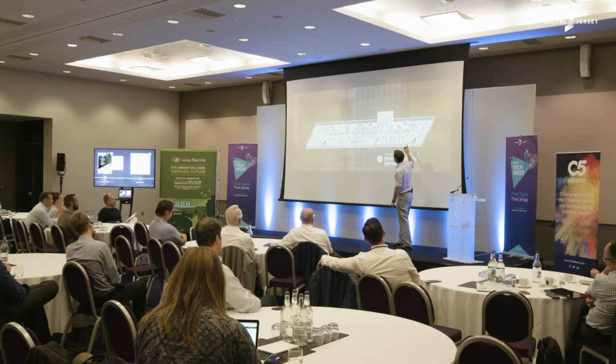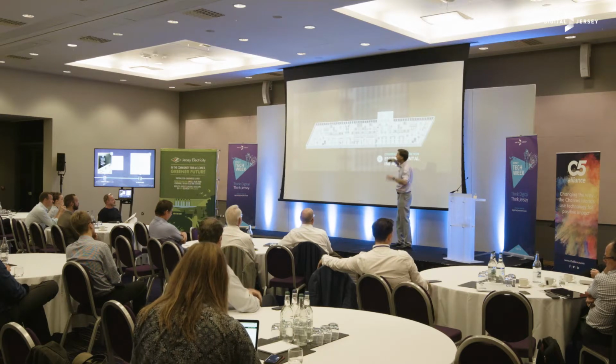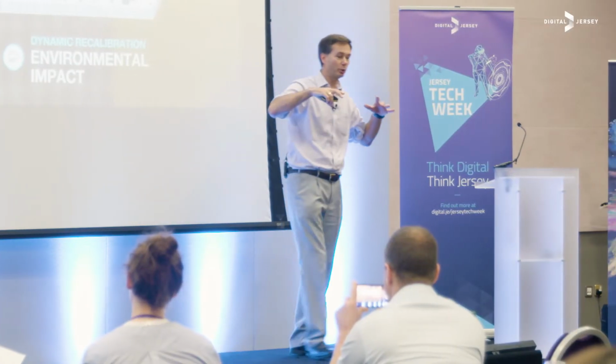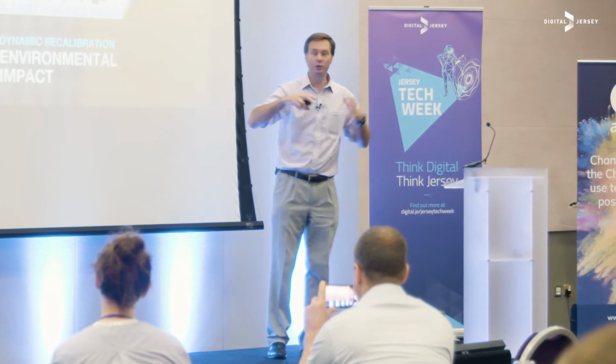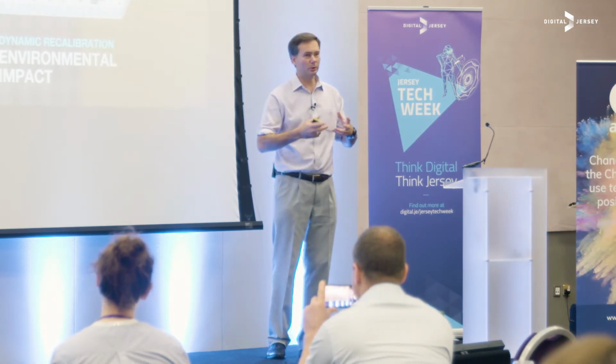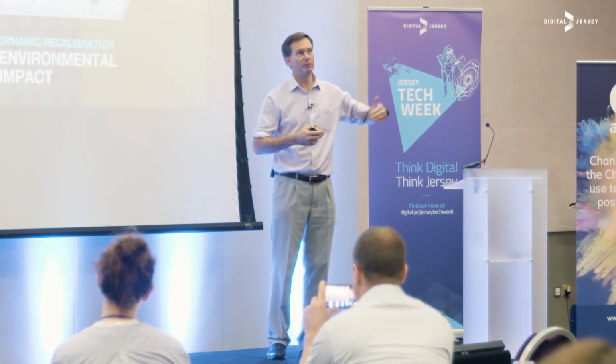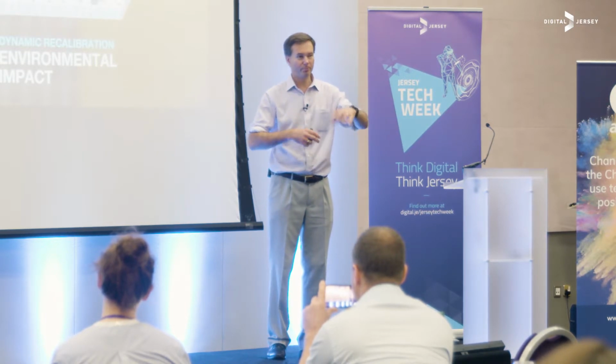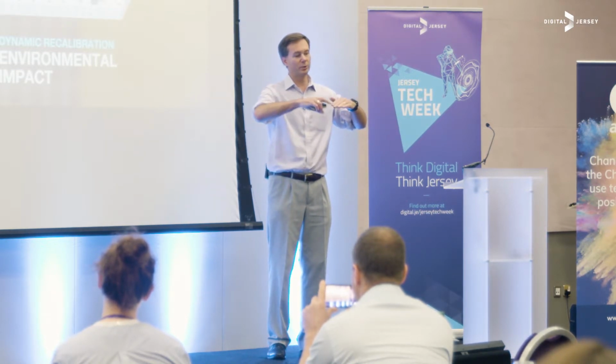And again, it's trying to make a model, trying to net out the difference between what the heating system is causing, sort of natural ventilation, and what the people in the room are causing. So we net off the number of people invited to the meeting for a number of time, which generates a model of what the CO2 should do in there.